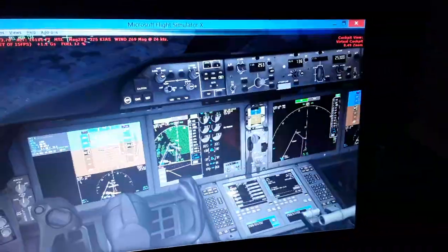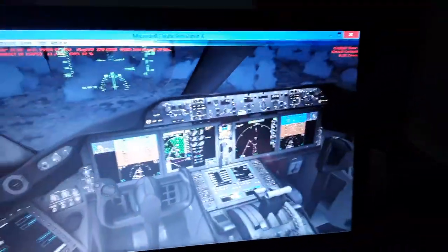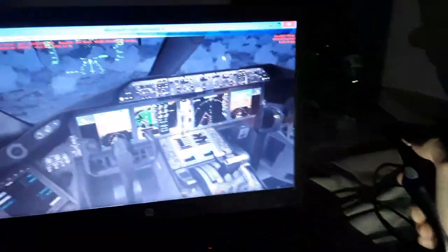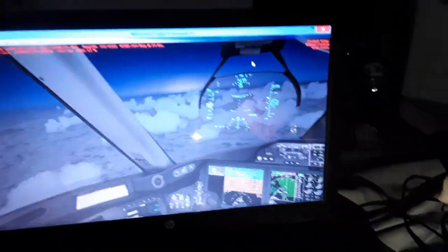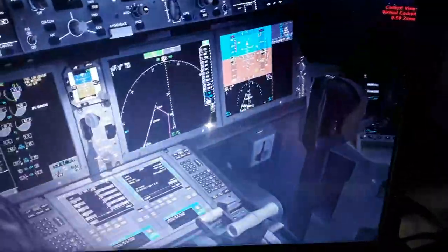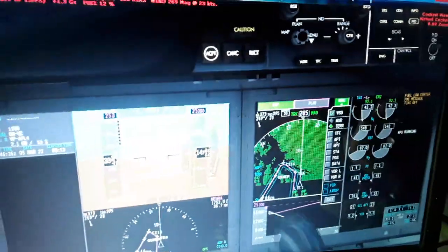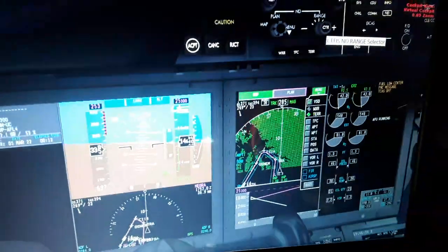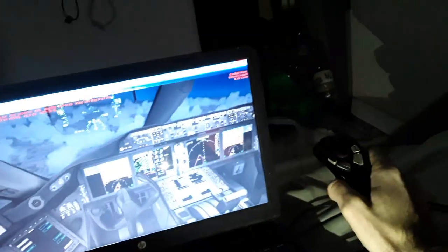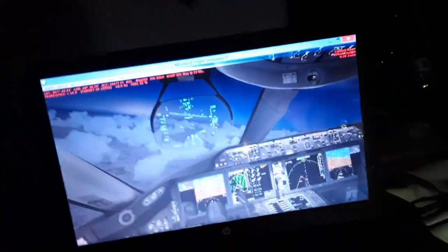This is a little bit more idle thrust over here, and trim down the horizontal tail of the aircraft. You can see both sides that we follow correctly over here. The flight plan, we need to start the turn now over here for the approach, terminal approach.